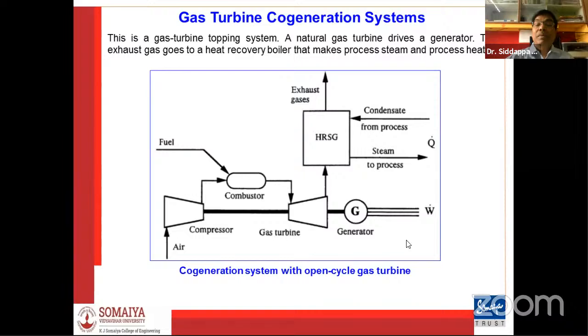And if it is still lower, then you can use it for heating the air which we are sending to the combustion chamber, and some devices can use the hot air for different applications. But using hot air at the initial condition in gas turbine power plants will affect the compressor power a lot. Therefore, generally we take the air from the atmosphere, at the minimum possible normal temperature.